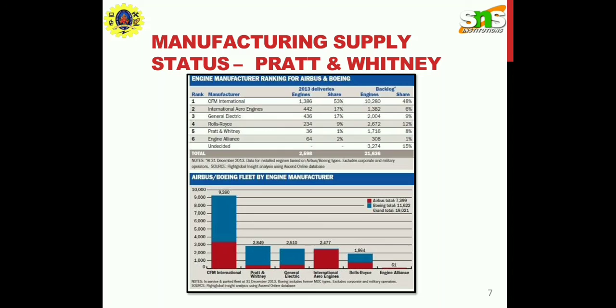Turbo machines can finally be classified by the pressure changes across the blade. Impulse turbo machines operate by accelerating and changing the flow direction of fluid flow through a stationary nozzle, and the nozzle serves to change the incoming pressure into velocity. The enthalpy of the fluid decreases as the velocity increases, and the pressure and enthalpy drop over the rotor blade is minimal.